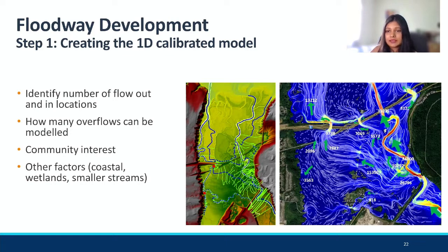And the first thing after we identified was just to lay out our 1D model cross sections, and you can see from these number of overflow paths, the number of 1D models we thought we were gonna have to calibrate to the 2D model, right? But then you can see like the figure in the center, it's a lot of models. Usually we don't have a lot of budget, and every model is not necessary to be calibrated or might not convey that much flow. So from there, we tried to filter and focus on which areas are more important or the community has concerns.